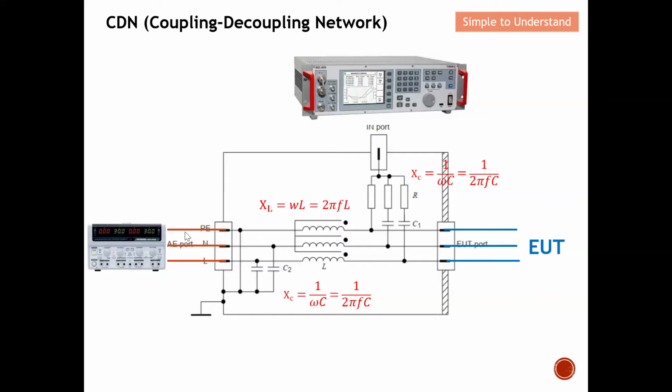Now let's take a look at another scenario, which is from the noise source. Over here, I inject my noise source. Once I inject it, you can see that it will propagate here. The noise source that I inject typically has a higher frequency. Once the frequency is considered high, this number will be a very big number, or a quite substantial big number. 1 over a very big number will be almost 0. So this almost becomes a short circuit under high frequency.